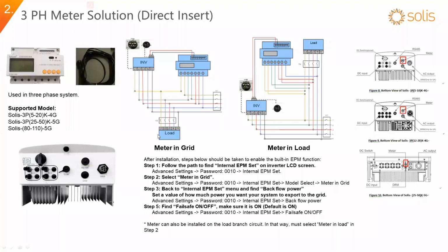RS-485 has interference issues with the power line in the same cable. The communication line should not be placed in the same cable with the power line.